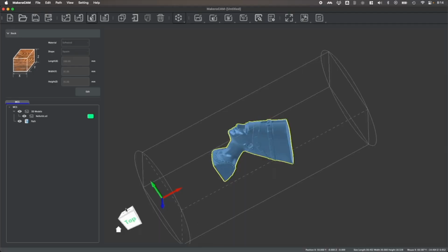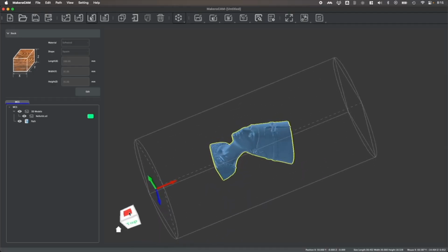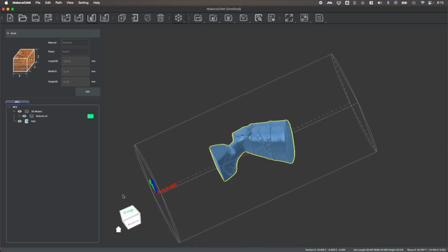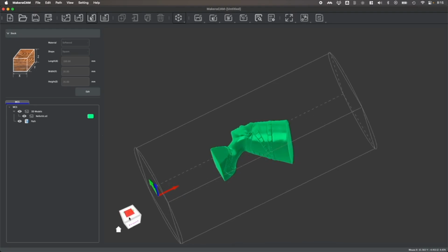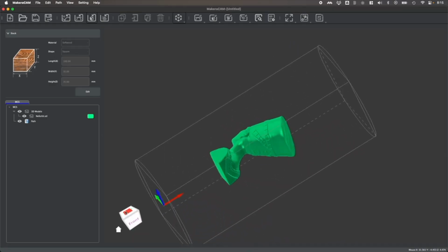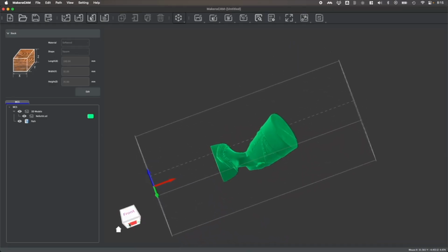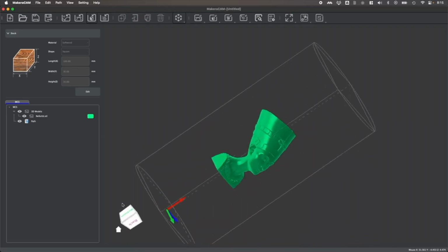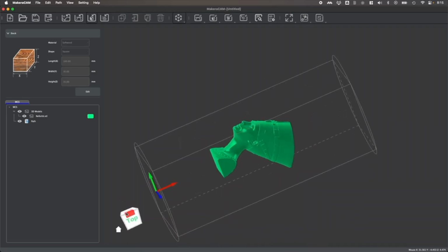Before we generate the toolpaths for a 3-dimensional relief file like this, we first must talk about tabs. Tabs, like with a 3-axis project, will hold on to the part while machining. But unlike with a 3-axis contour that you can create with a 2D or 3D file, 4th-axis tabs need to be drawn unique to the model that you import.